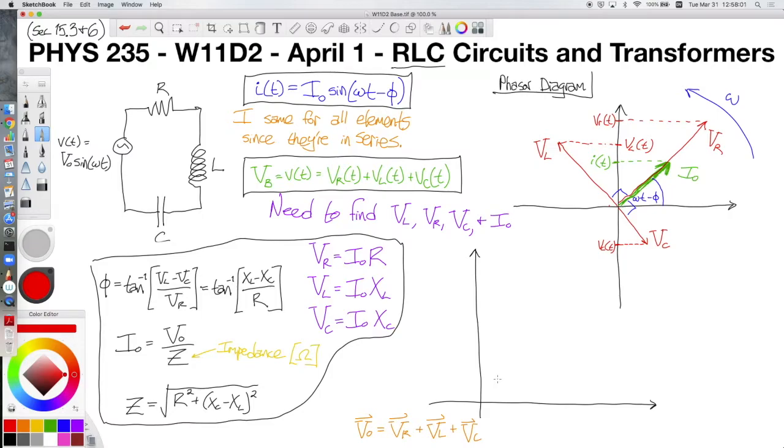So that means we might have our V sub R vector, capital V of R, the maximum resistor voltage, pointing this way. And then at a right angle to that, we have another vector that is VL minus VC. This is why I made the VC vector shorter, just so it's clear that this vector would point up and left, not down and right. So this has now accounted for each of our three voltages across our circuit elements, at least the maximum voltages across them.